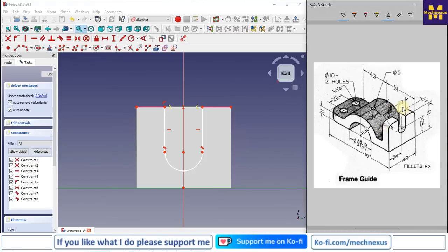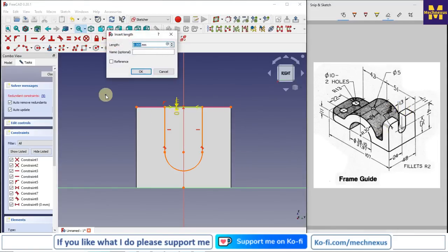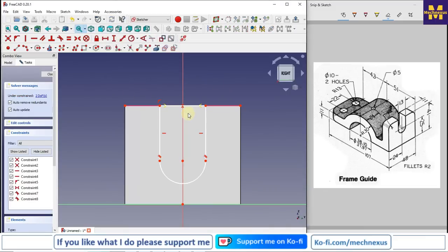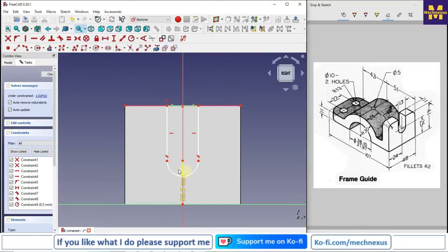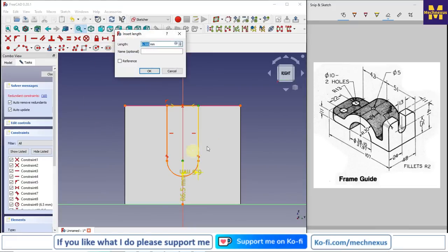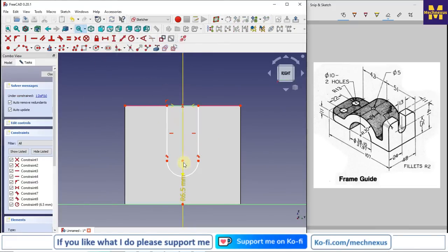and we can see here slot is 13, so I will give it a radius 6.5, and now from the bottom it is 25 and overall height is 41. So I will select these 2 points, and it is horizontal.